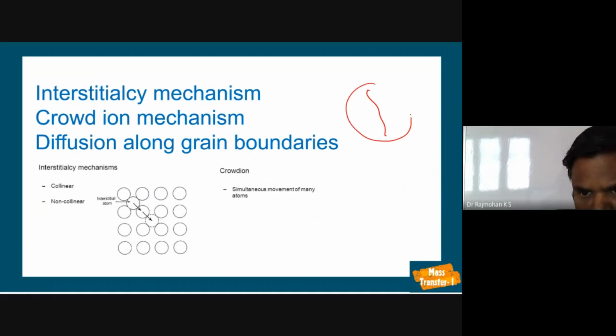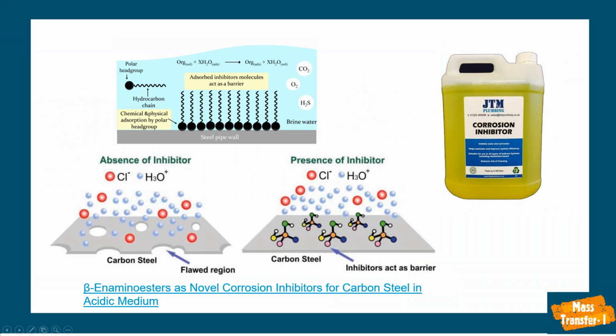In any metal or any alloy, when you have added some materials, what happens, even though you have distributed them? See, if you add some materials into the metal to improve the properties, for example, a corrosion inhibitor. Corrosion inhibitor is available in all forms, okay, solid, liquid and vapor form. So if you consider solid phase corrosion inhibitors, when these are incorporated into the metal composition, with time, when they come in contact with oxygen, these corrosion inhibitors will align themselves along the grain boundaries and protect the material.